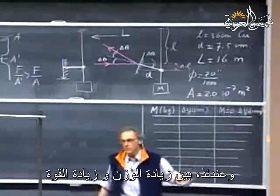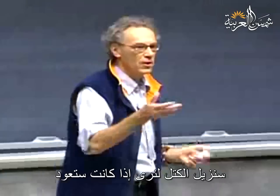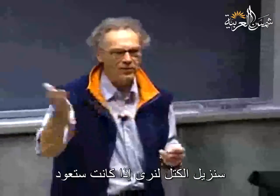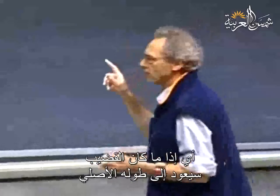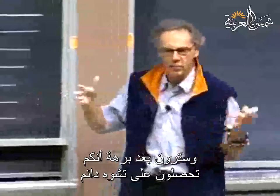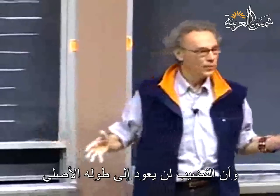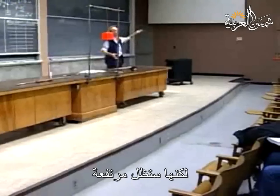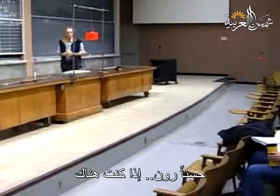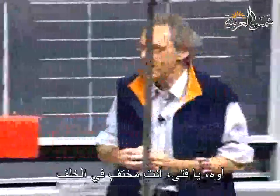And then in between increasing the weight, increasing the force, we will take the masses off to see whether the length of the rod returns to the original length. And you will see after a while that you get permanent deformation, then it no longer comes back to its original length. In other words, the laser spot will not return to 0 on the wall, but it will stay higher.